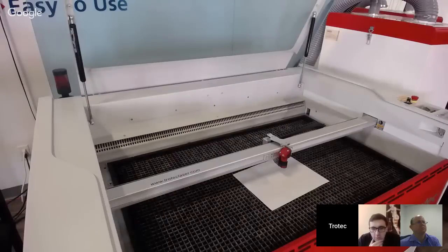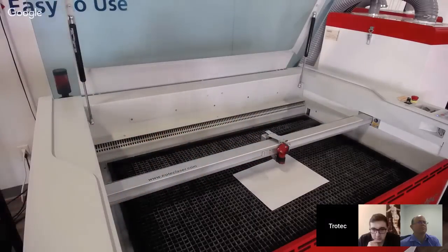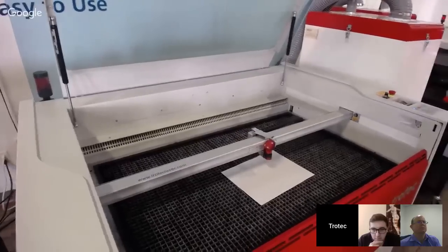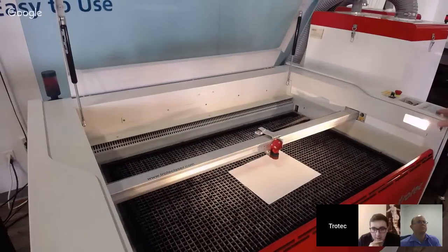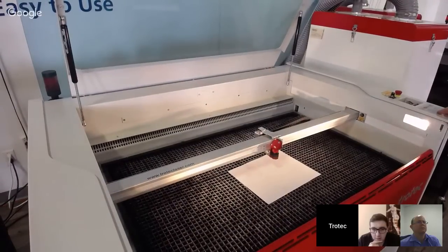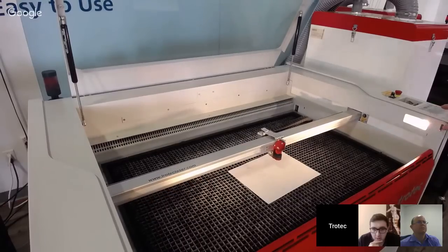Oh, wait, Anthony, sorry, before you go back, can you show them the keypad as well, that you can move the head with the keypad, not just manually? Yeah, we can show you that. So right now our laser's in standby mode, which allows us to move this around freely, which is great. Or as Lev was saying, you can come here and take it out of standby mode using the power button. And now using your D-pad, or directional pad on your laser, you can now move your laser like so. Yeah, and you want to make sure not to move it manually when it's not in standby mode. That's correct.